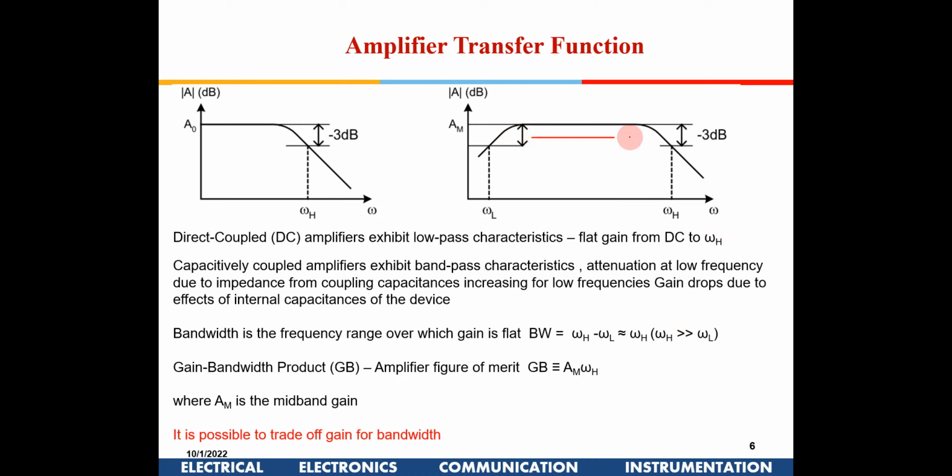The desired frequencies should fall here. Okay, you should not try to put your desired frequencies at these limits. Understood? Because of these RC values, you will have 3 dB loss already out here, right? So your desired frequencies should be within here. At 3 dB, you will have to understand that at these frequencies, the power is almost half. So you have to keep that in mind.